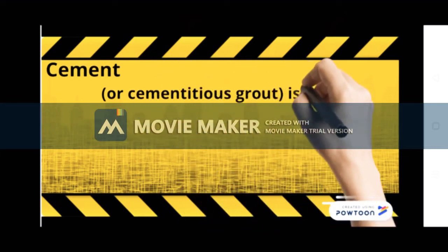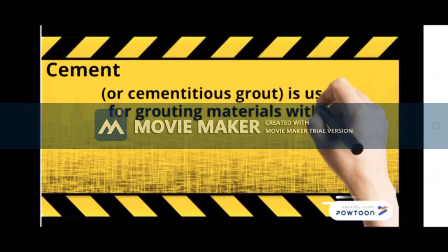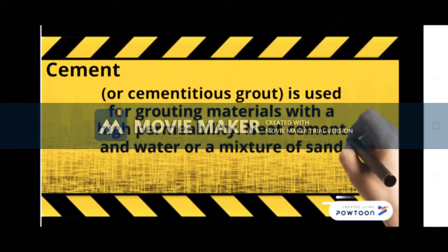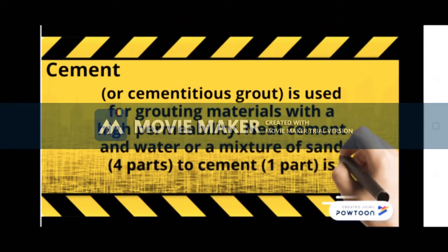Cement or cementitious grout is used for grouting materials with a high permeability. Neat cement and water or a mixture of sand, 4 parts, to cement, 1 part, is the usual composition.